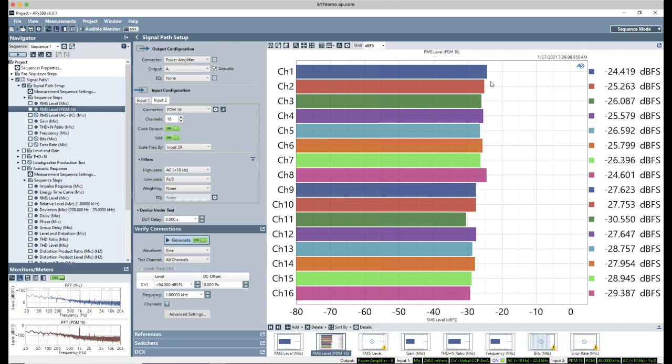You do see some effects here of the fact that my physical setup has the source speaker quite close to the PDM microphones. So we are actually seeing a little bit of effect of the sound pressure diminishing noticeably between the closest and the furthest microphone. But we can see we're in that range. These PDM microphones, I think their spec is officially minus 26 dBFS at 1 Pascal.